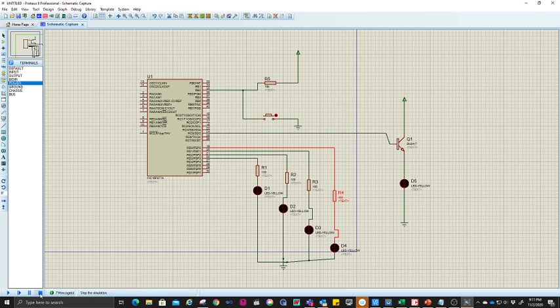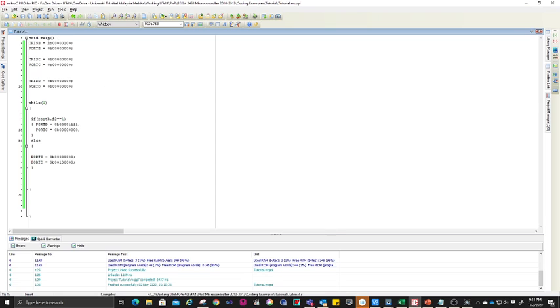Okay, let's try. You can see that the LED is much brighter. Okay, so I turn on this one. You can see that this gives the signal out 5 volt and turns on the base of the transistor, and then the power goes down and turns on the LED over here. So you can see how my switch is working by using this if else statement. So you can play around with a lot of ideas, and the code is quite simple basically, as long as you understand how to work on that.